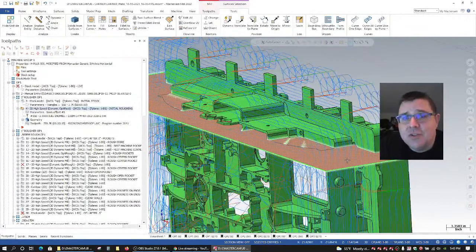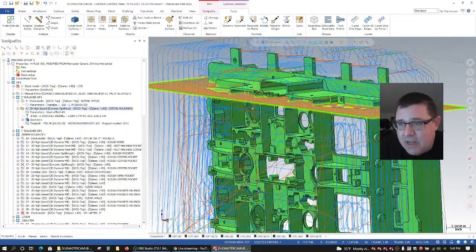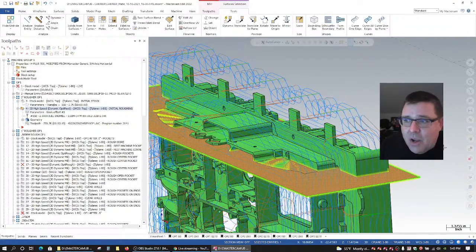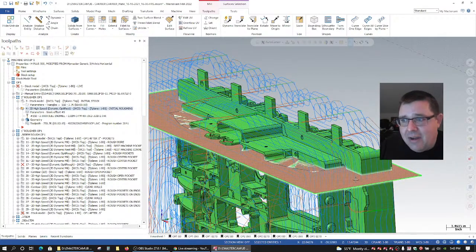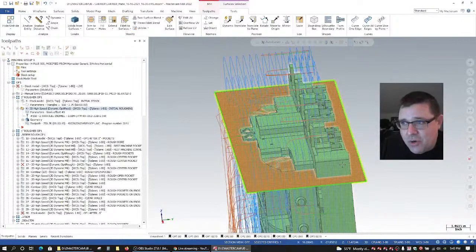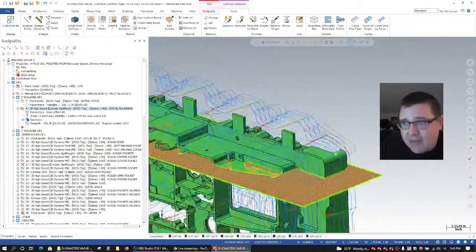If I'm using it as drive geometry instead of avoidance geometry, I usually call that a run-out surface. So I've got some surface that I'm using as a depth limit where I don't want the toolpath to go any deeper than that. And here I would then select again where I showed selecting the individual top faces as opposed to selecting the entire model.